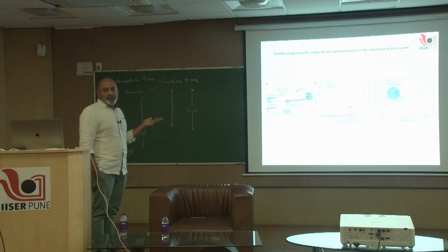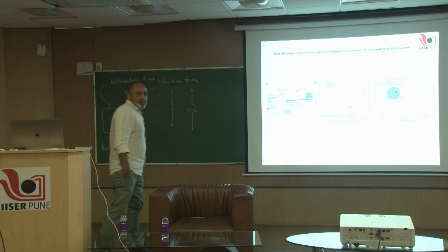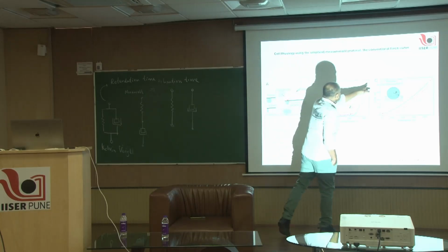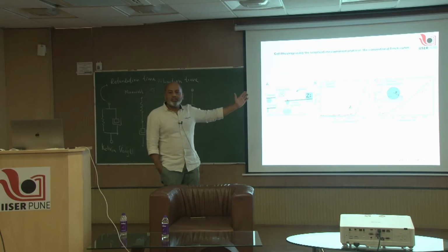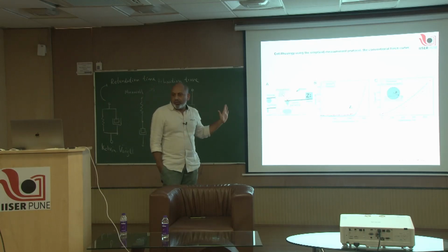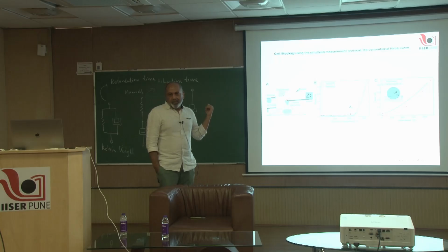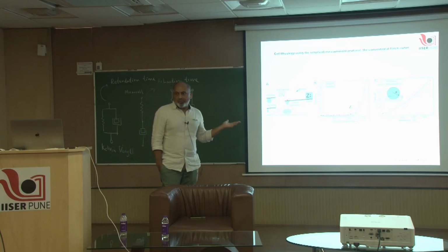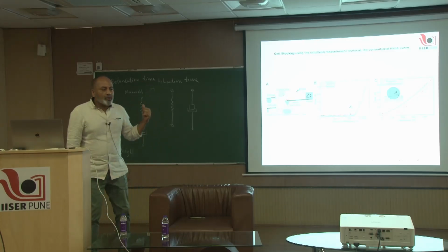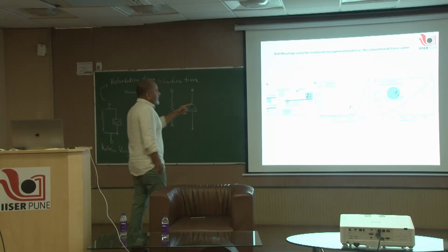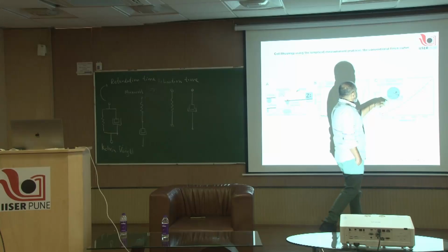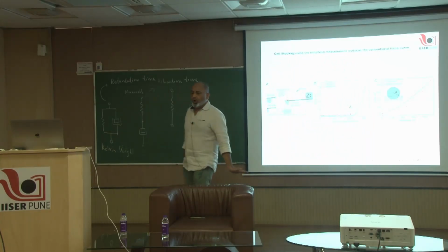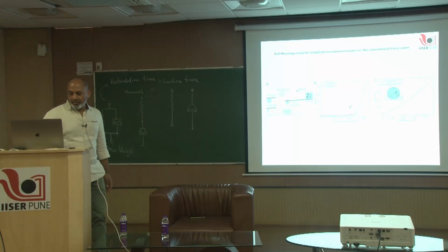This hysteresis is something that most cell mechanics data ignores; the part while you come back is ignored. We tend to fit Young's modulus or Hertzian contact mechanics, assuming a fully elastic solid, only to the approach part and ignore the retract. And ignoring retract, basically you are throwing away a lot of information. Okay, and I will not go into the procedural details. This is what people normally do. You only apply Hertz's model to the approach part, and this is the model. And then you know what the Young's modulus is, as a fit parameter one obtains.